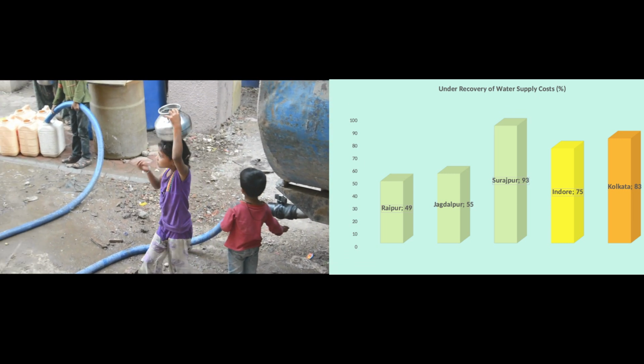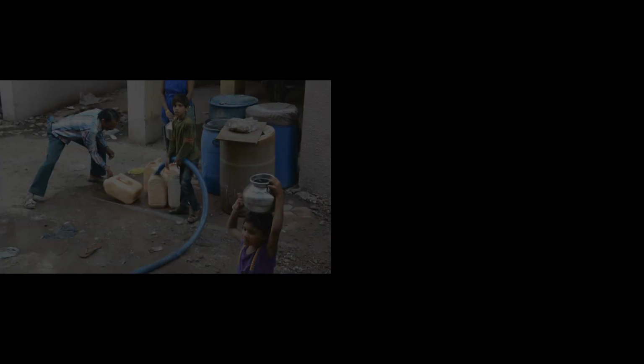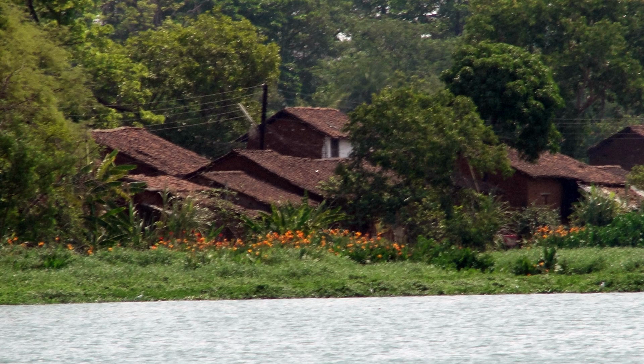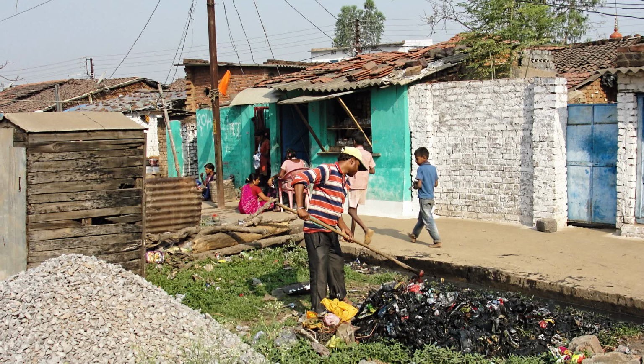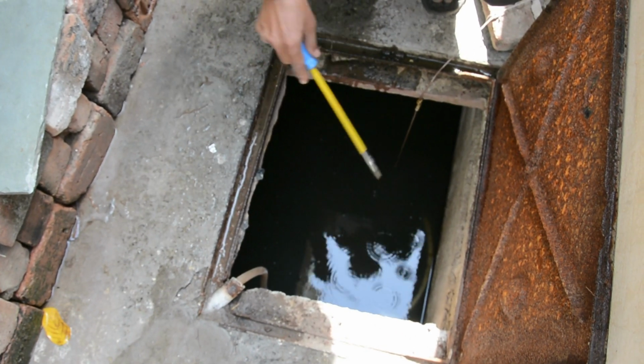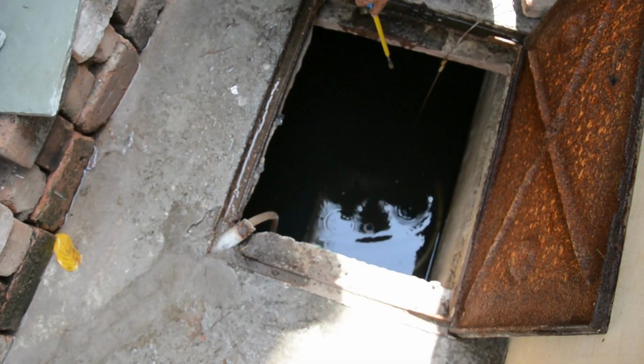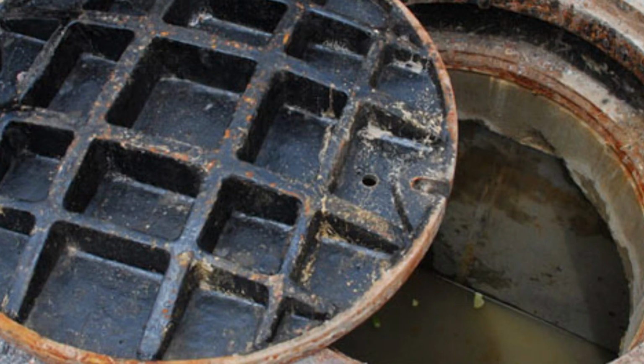Towns in Chhattisgarh, except for the new greenfield capital town of Naya Raipur, do not have underground sewerage and sewage treatment facilities, and they use grey water flows in open or covered drains next to the roads along with the storm water. The black water is treated in septic tanks with the overflow going to these roadside drains, polluting both surface and groundwater as tests have shown.